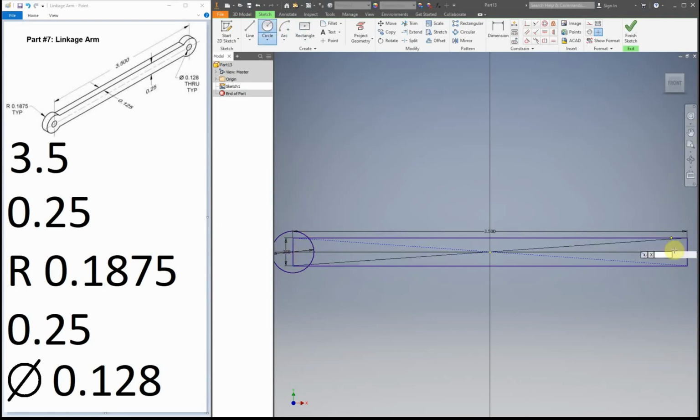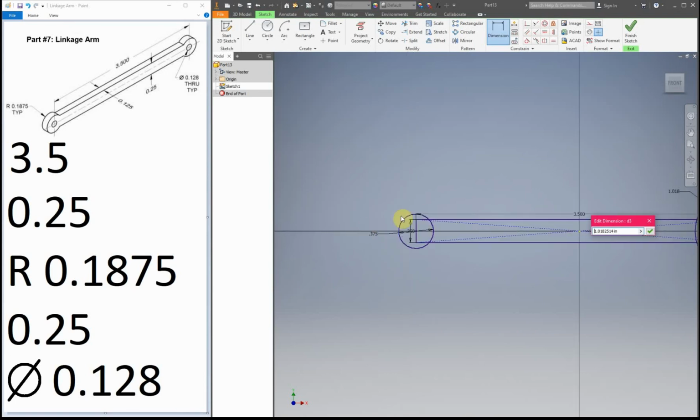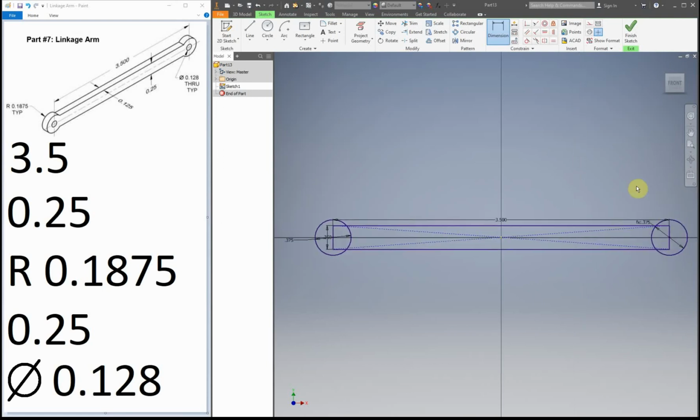We're now going to put in a circle, and I'm going to make this a little bit larger so I can show you something. One thing you could do is make the same dimension. You can click on the dimension tool, and then, oh, I need to zoom out. We can click on this, and then it pulls in the same number, as long as it would actually delete the other stuff. Or, what I can do, oh, see how it has FX? That just kind of means it's referenced somewhere else. So I'm going to delete that. And it's now green again, so I can move it around.